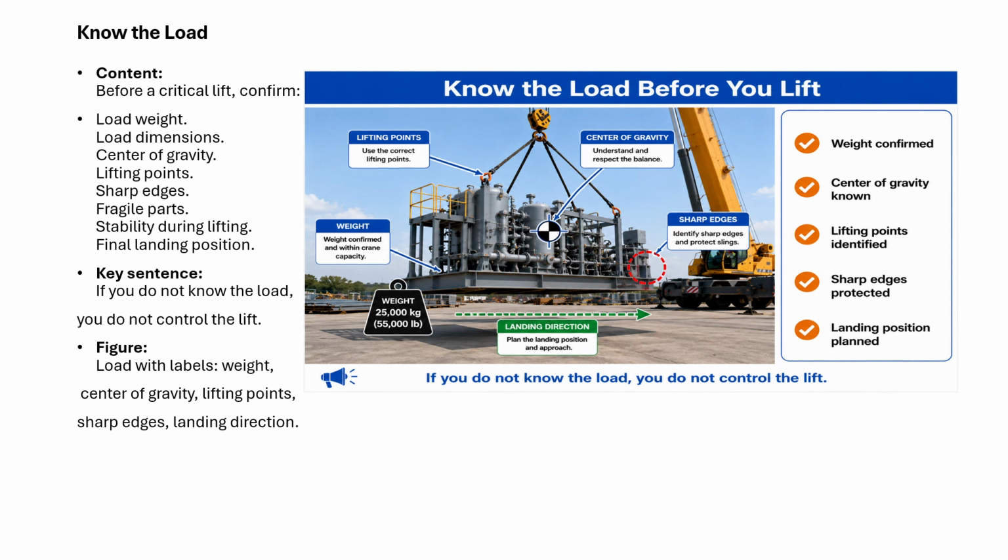Know the load. Before the critical lift, confirm load weight, load dimensions, center of gravity, lifting points, sharp edges, fragile parts, stability during the lift, and final landing position. Key sentence: if you don't know the load, you can't control the lift.